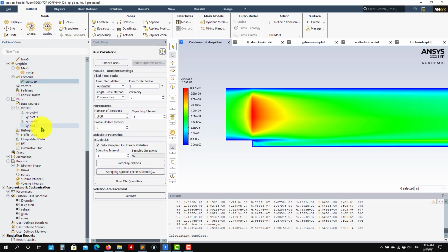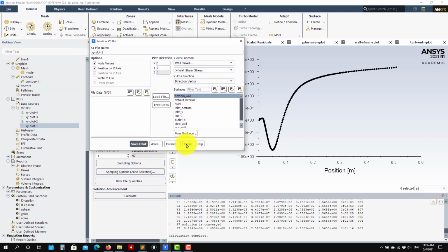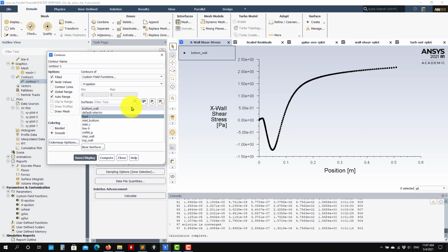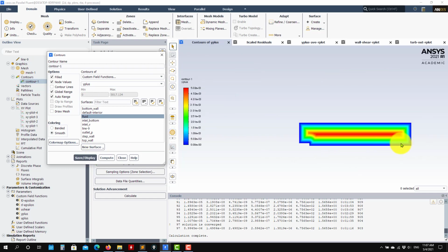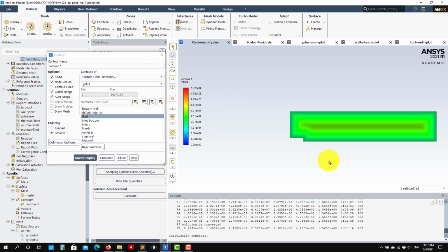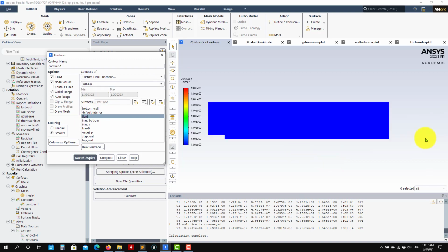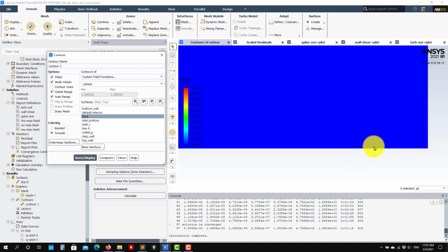So pretty much we have addressed everything here. So let me go back here. We have all these plots, your quantities, and again here also in these custom fields, I think we have access to also again y plus. So see that we're computing y plus, and you have access to that value in all the fields. So you have access to u shear. Remember that u shear will be constant because we computed it at one point. So everything that you add, you get access.